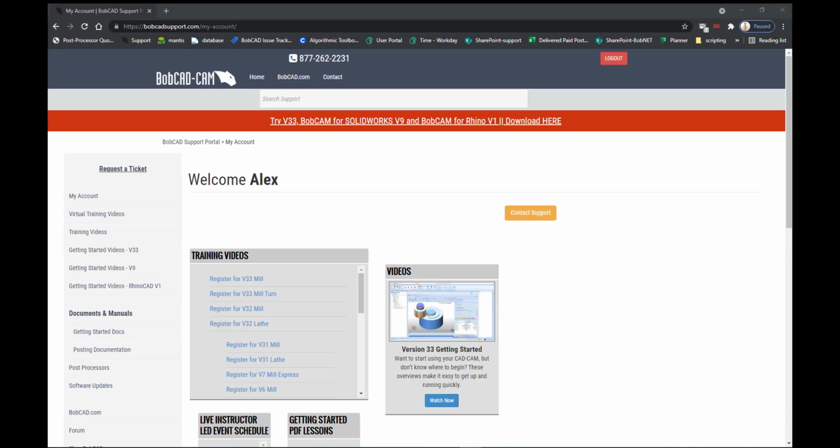In this video, we're going to cover how to request a new post processor for your controller. Now, prior to requesting a post processor, you need to first make sure that there isn't a post already available for you on our online library, or at least something close to what you need, because it's always going to be quicker to request a modification to one of these posts than it is to request an entirely new post.